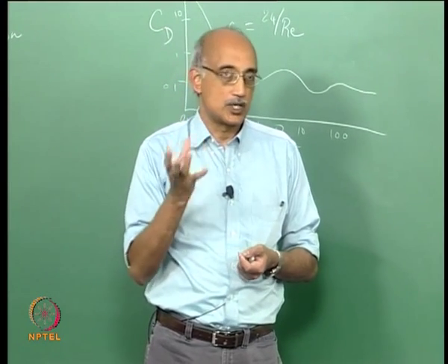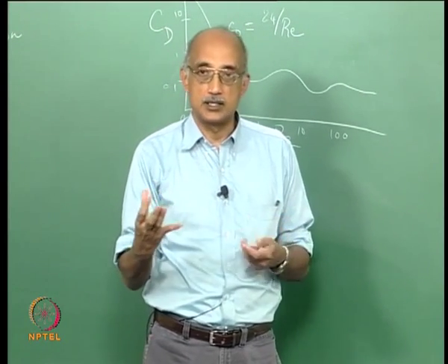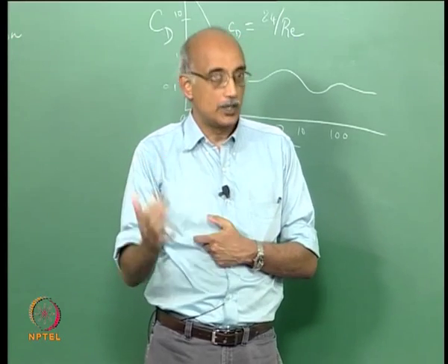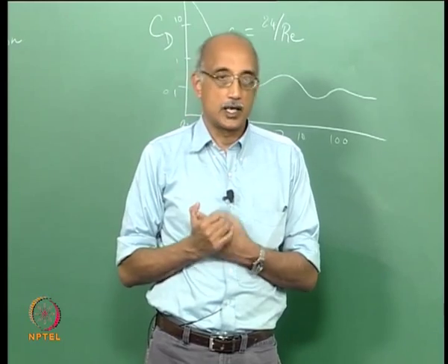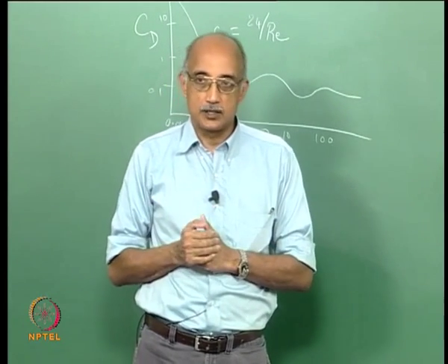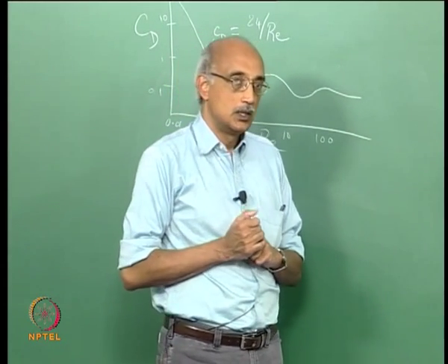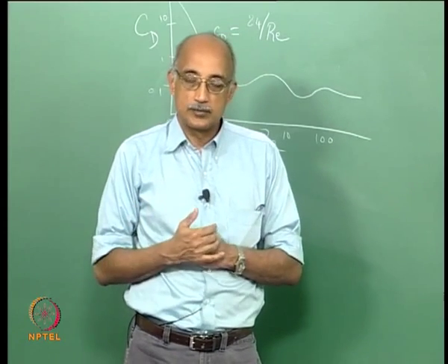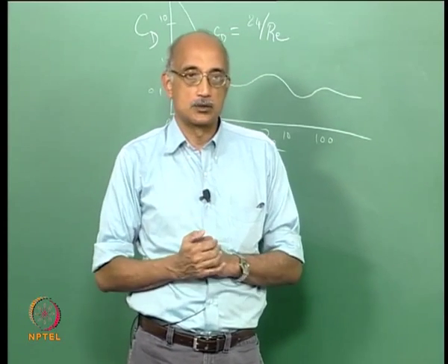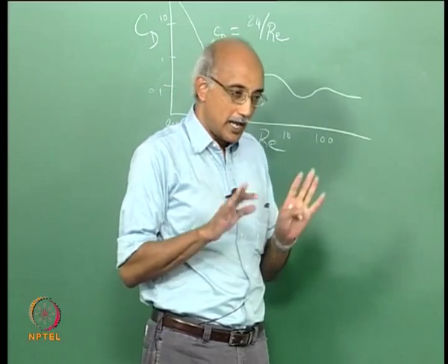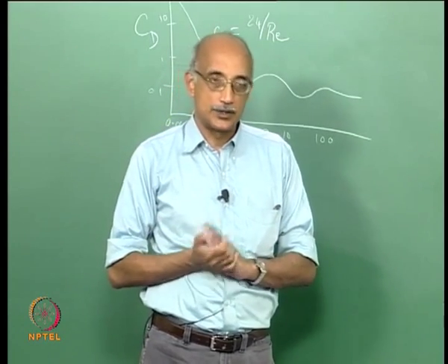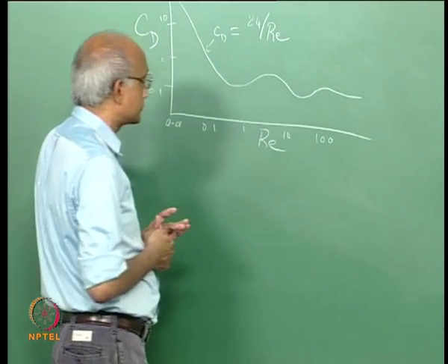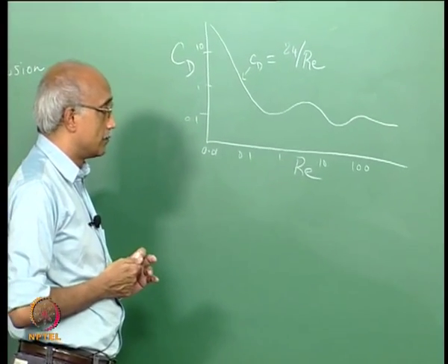If this object is impacted by several eddies in a period of time, it will experience high drag, but there may be periods of time where, again, given the unpredictable nature of fully turbulent flow, the particle may experience low drag. But if you integrate drag force over time, essentially laminar versus turbulent does not have a significant influence on the drag force that is experienced by the particle.